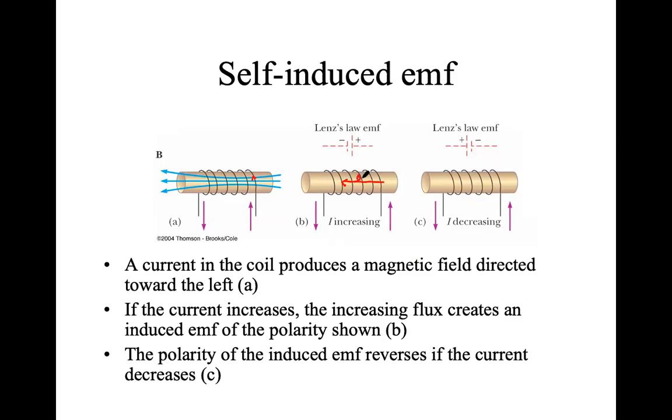So that's the direction of the magnetic field's change. There will be a current induced in the opposite direction to oppose that increase. So that's the change by the current increasing. There will be, and I always draw it smaller, a magnetic field induced in the opposite direction to oppose that change in flux. It's almost as if a little battery is created in this coil. That's the induced current, which is going that way to create this induced magnetic field to oppose the change in the magnetic field by increasing the current from the source at the very start.